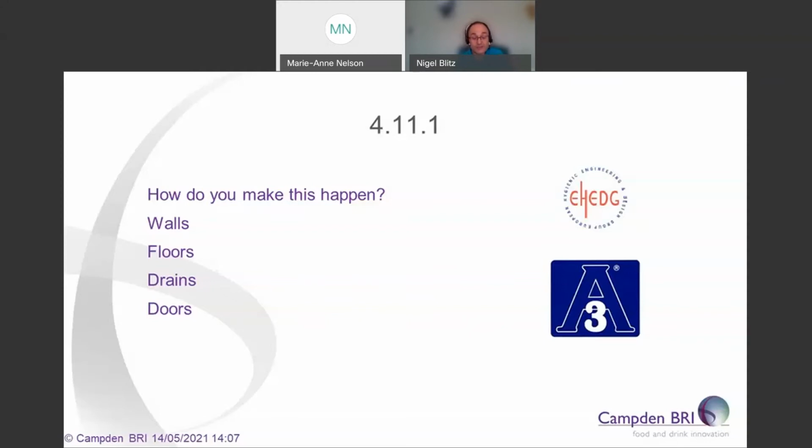So doors should be easy to clean and, when necessary, to disinfect. Doors should have good inspection access. Doors should be self-closing and equipped with kick plates and push plates. Sliding doors should have all gaps closed between the door and the frame and closed with gaskets of rubber or brush strips, but no brush strips in high hygiene areas.